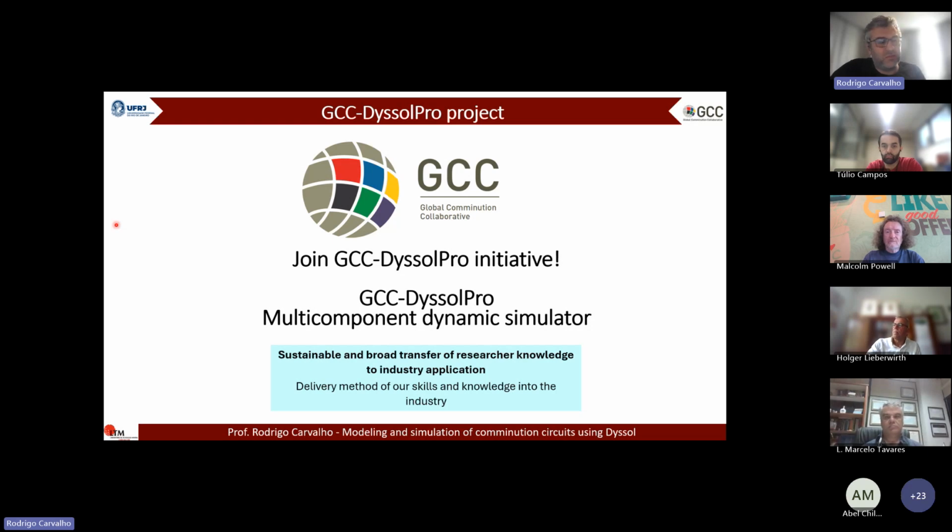But there's a whole other topic for discussion that perhaps in the future we can tackle. When I talk about the GCC Dyssol Pro initiative, we have the control tools there. One of the validation cases that we performed last year was controlling a crusher plant with silo levels and bin levels. Without that, a crusher plant wouldn't operate well. We need to shut off some feeders in order to avoid overfilling a silo or reaching the maximum capacity of stockpiles. You wouldn't be able to do that using just a steady state simulator. This is the message that I have.